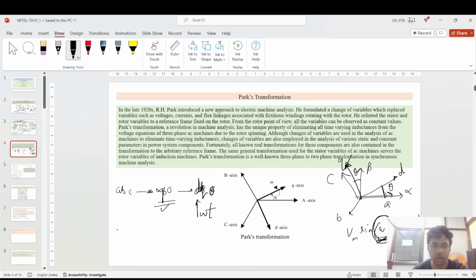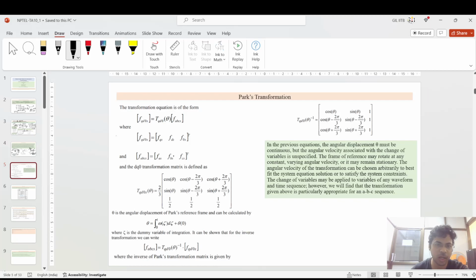This doesn't need any synchronously rotating frame angle. So how do you actually implement that? We take the VABC as a reference, then fit it to the PLL, and the PLL gives the measurement of the frequency and the theta component. Then you use this theta inside the DQ naught frame for conversion of ABC to DQ naught, but you don't need anything for the alpha beta frame. And the same applies when you are converting from DQ naught to ABC.